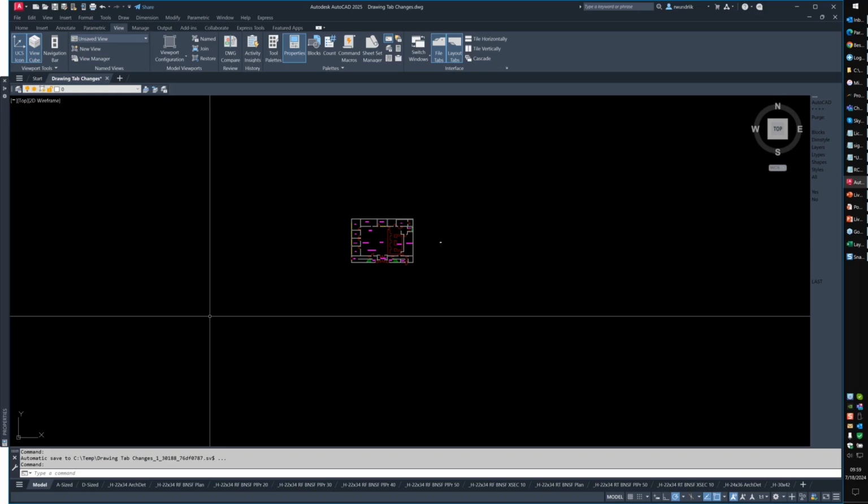And you should have D-view twist, but you have to do it inside a viewport, and you have to do it with an unlocked viewport. You type in D-view, you hit enter, and then you can get TW for twist.